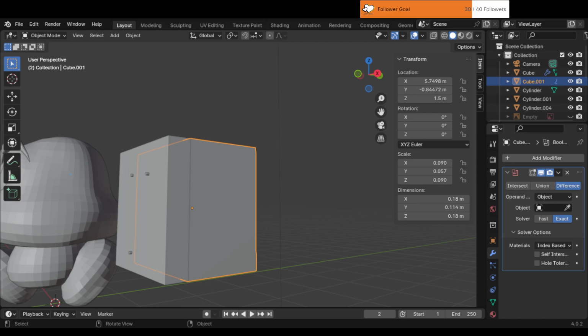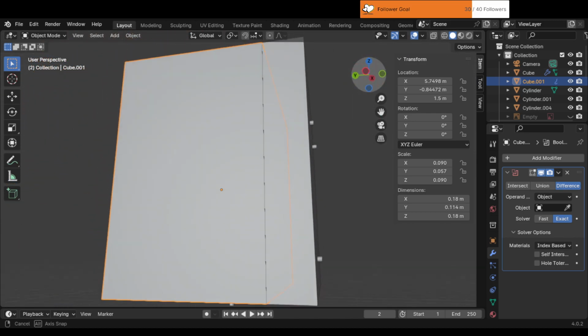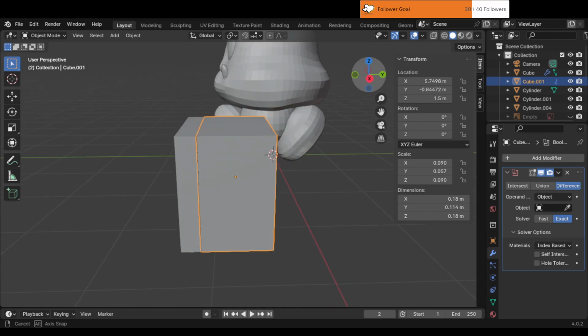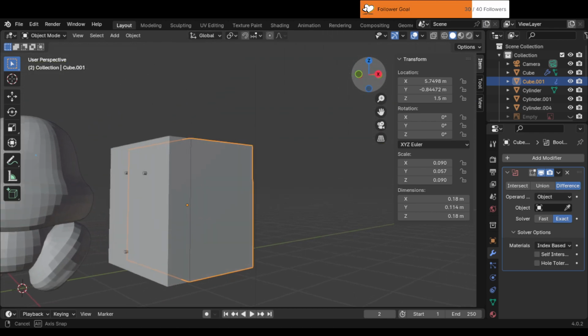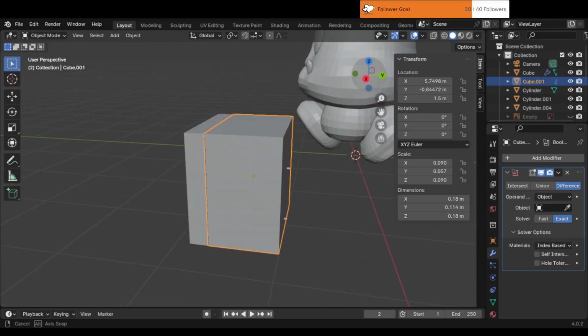If you find that moving the container mesh does not change the result of the Boolean operation in Blender, there might be a few issues causing this behavior. Here are some troubleshooting steps to help you resolve the issue. 1. Check the modifier stack. Boolean modifier. Ensure the Boolean modifier is active and applied to the correct object, your container. Operation. Verify the operation, e.g. difference, and the target object, your 3D model, in the Boolean modifier settings.